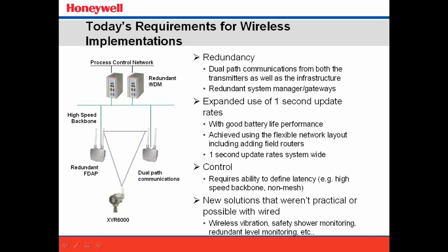So this made it much easier. When the safety shower was activated, not only did it alarm, it also historized that event. So through the DCS, through the historization they already had, they had a record that they were testing the safety showers and eyewash stations. That was a cool little thing that wasn't a selling point of the system, but it happened on the back end, and they were pretty happy for it.